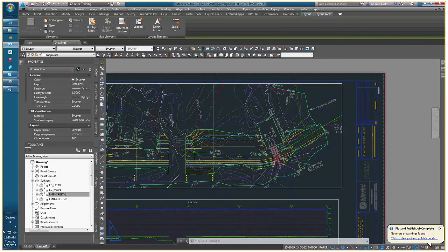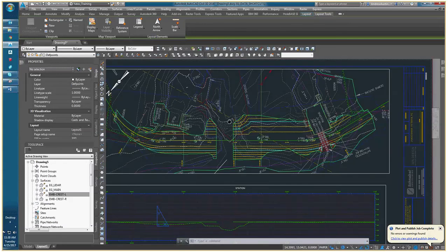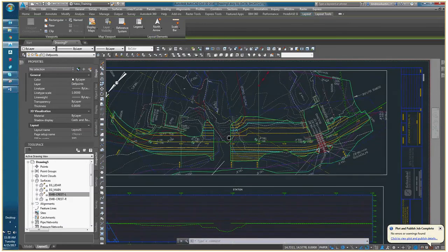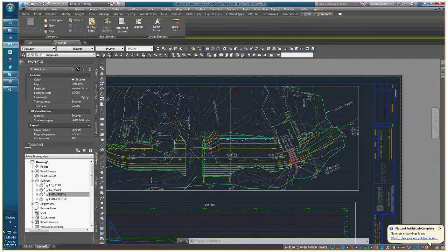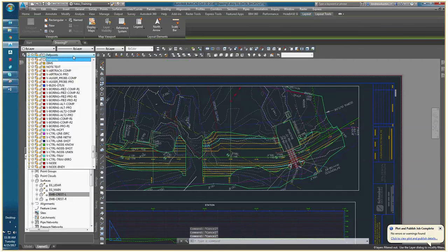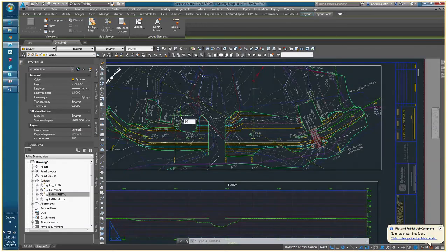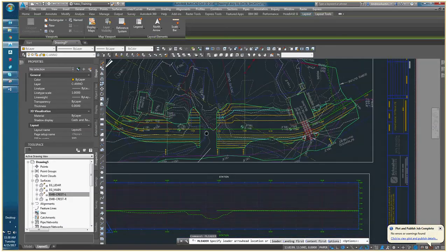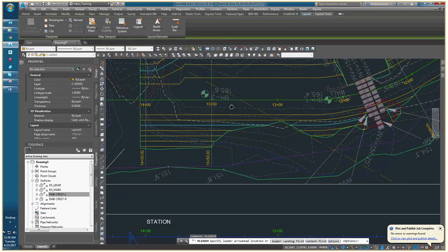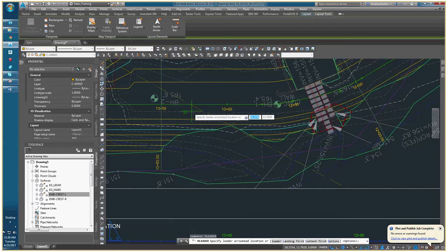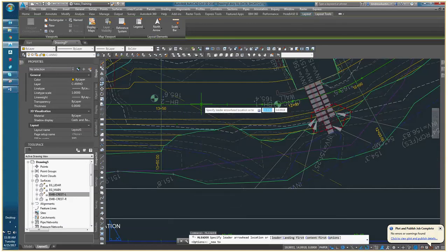Here in Greensboro, we tend to annotate almost everything in paper space. And there are a number of reasons for this. And there's at least one drawback to doing it this way. And so if I first make sure I'm on the right layer, we're going to go to the C-Anno layer and drop in a multi-leader. So the multi-leader command is mleader. And these are style-based as well. But I'm going to use the mleader command, and I'm going to shift right-click and grab the nearest because I just want to grab this alignment.